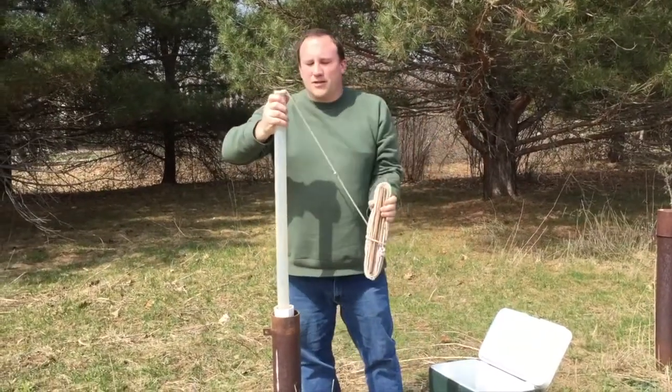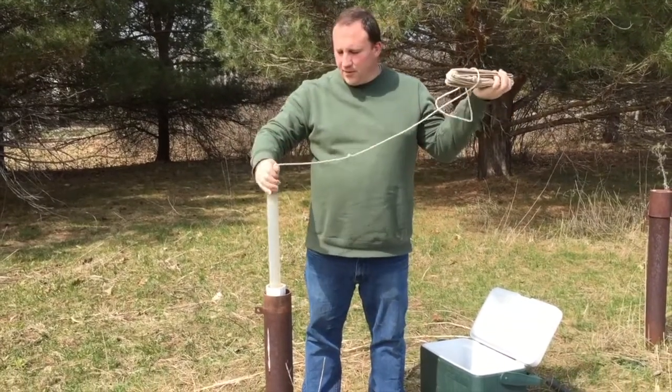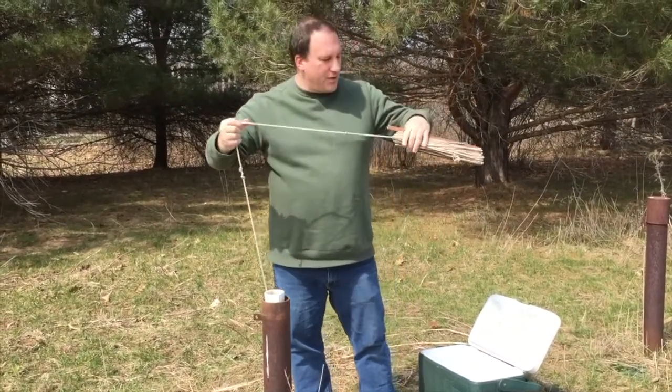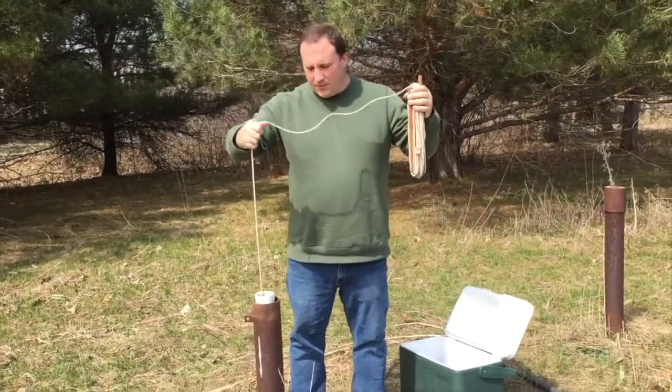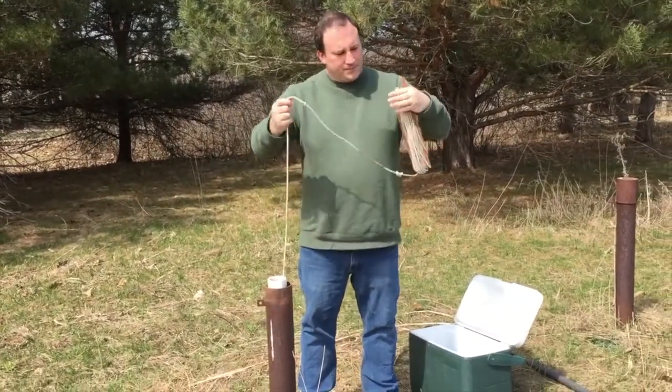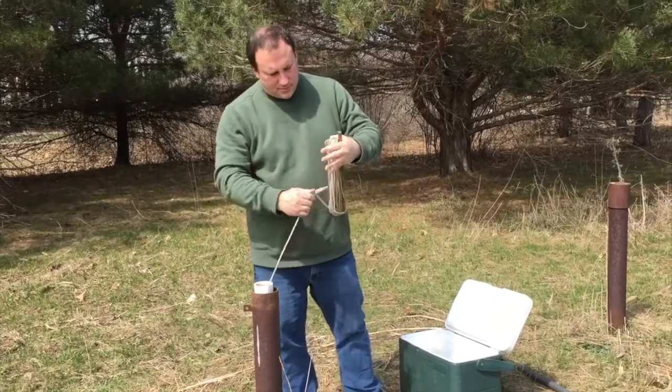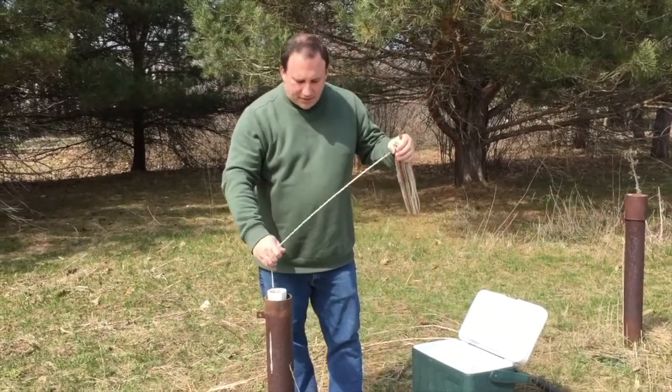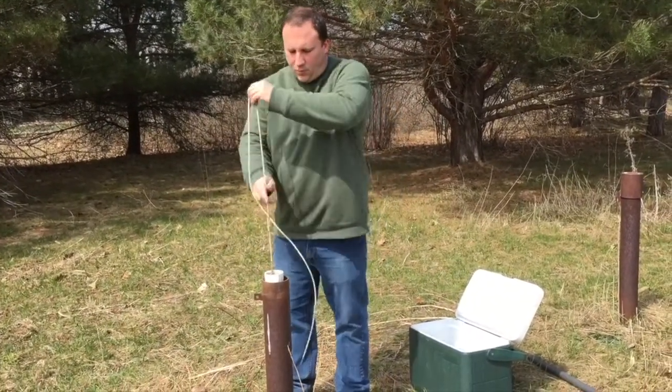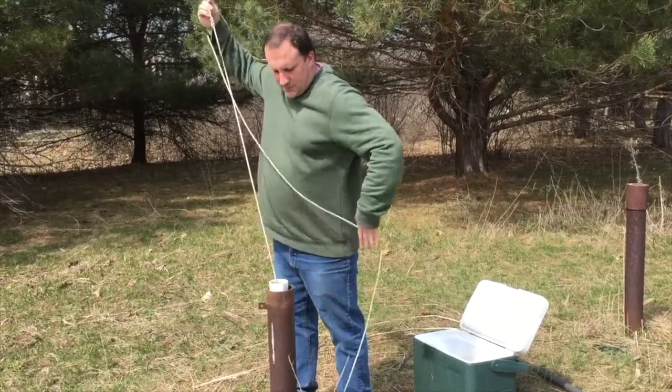We're at monitoring well 2 right now, and I thought I would just do another bailing test just so we can compare pH and conductivity with the first well, monitoring well 1. So I'm going to take a couple bailers out just so we can get something a little bit more representative down in the aquifer.